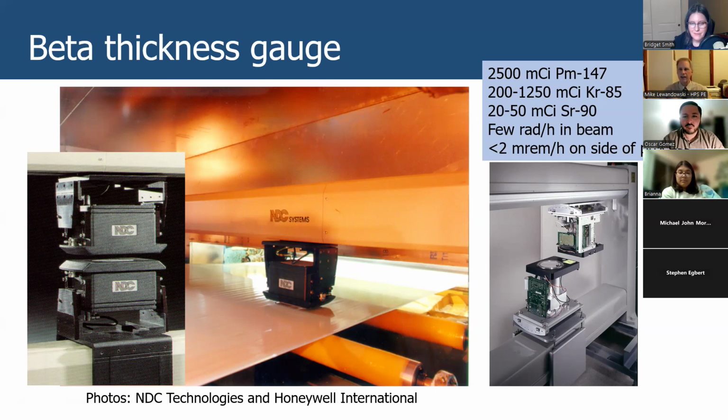we can now measure the thickness of our coated material from edge to edge, not just where we can reach to take a sample. So we can actually measure the entire material. And because we're doing an electronic, non-contact measurement, we're not causing any sort of destructive testing, right? Because it's electronic, we can determine that I to I naught ratio immediately, do the calculations through the computer, make a comparison to the tolerance, and all that happens immediately.